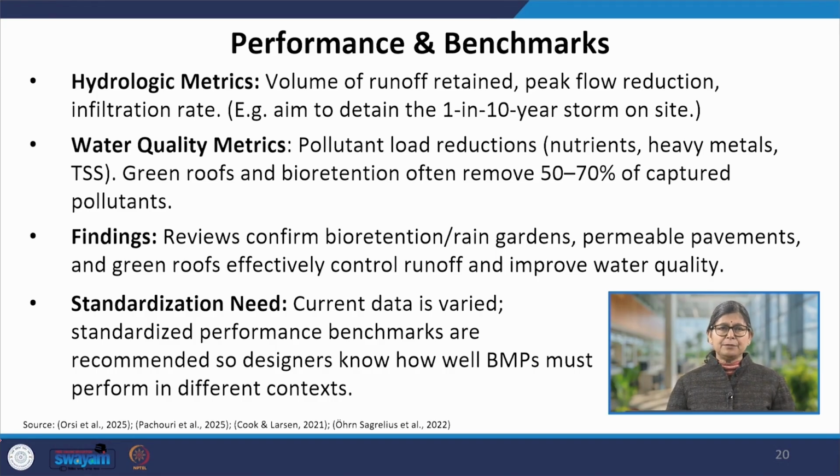The first one can be hydrologic, as we are discussing water. So volume of runoff retained, peak flow reduction, infiltration rate. Like we can have an aim to detain the 1 in 10-year storm on site. That can be a very good target.